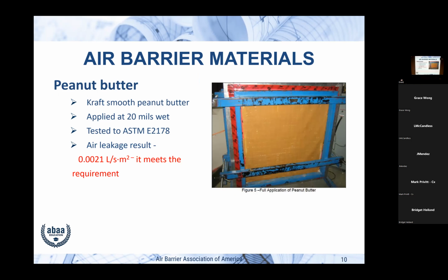Well, this is in liters, so the maximum air leakage can be 0.02. We threw another 0 in. And that's quite typical for all airborne materials. If you go to Imperial, it's 0.004. Almost every material, these guys in the room here, if you take a look at the air leakage rate of their material, put at least another 0 in there, sometimes 2. So we do some really tight.